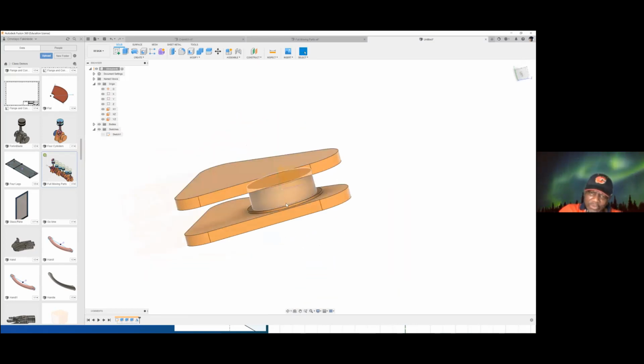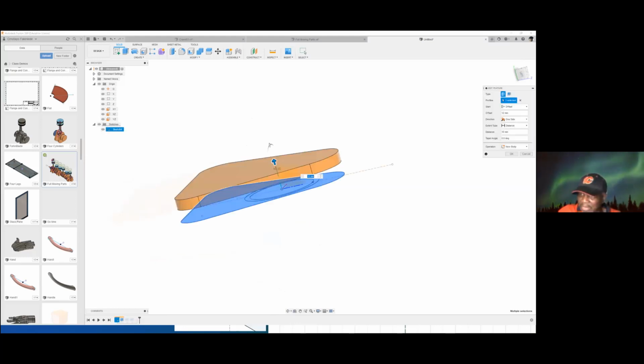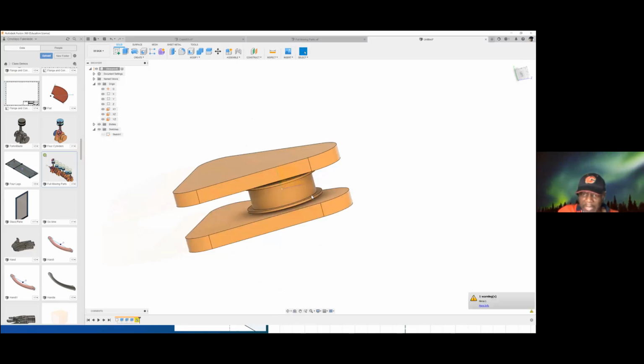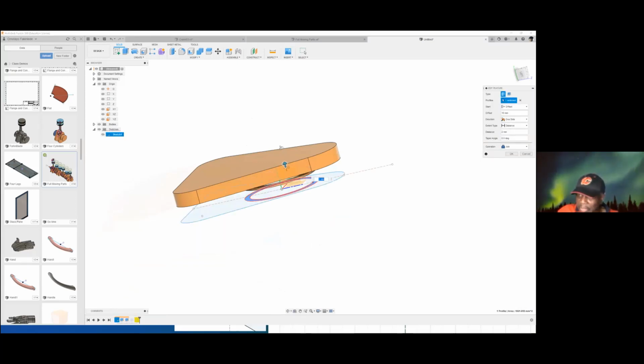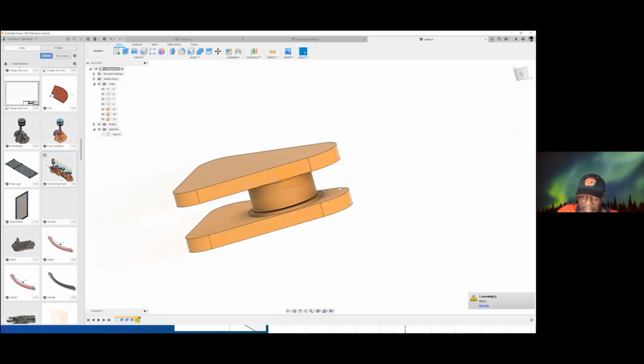If this distance is too small, we can go back and do an editing. If I edit this feature, maybe instead of making this offset 12, I make the offset 15, and I make the distance 13. Okay. And then the second extrusion, I can go again and edit the feature. That offset will now be 13, and the extruded distance will be 2 to join. And then let's see whether that is it.